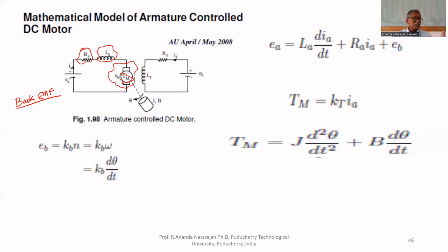What is a generator? If you rotate the armature in the magnetic field, EMF is induced. That is a generator, a DC generator. Because it cuts the flux, that's why EMF is generated. Here, it is the opposite, Fleming's left-hand rule. In a generator you rotate the coil in the magnetic flux, whereas here, instead of rotating, we are placing the coil in the magnetic field.